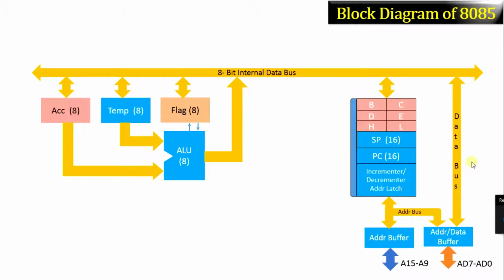So what we can do is multiplex those 8 lines on the address bus, because address and data will not be transmitted simultaneously by this IC. One time only the address will travel on the bus, and another time only data will travel on this bus. So what is the need for separate address and data buses? We will multiplex the data and address bus together. So here is AD0 to AD7, meaning the address and data bus. These 8 lines will carry the address as well as data.